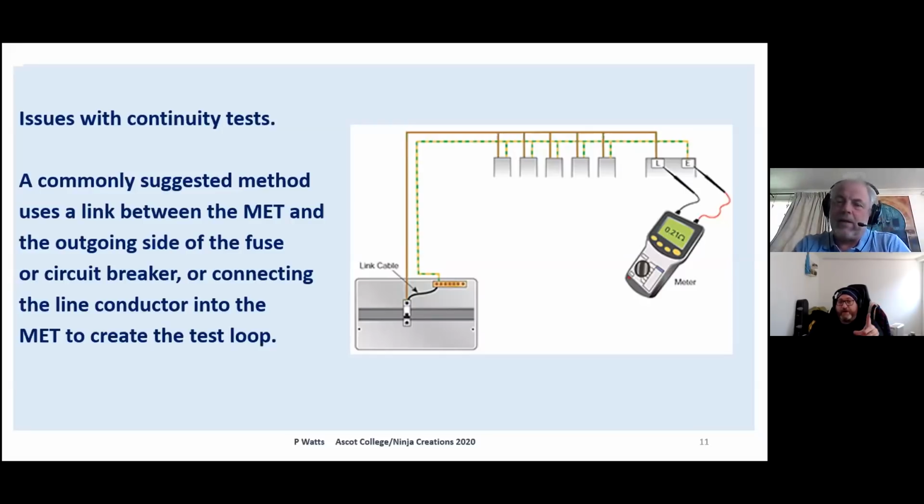We plugged it in because the site had this system where everything that was coming to site had been tested and checked, and that system had been in place. It was brand new. The person checking it didn't take that link out. It came in on site with all the certification, all the documentation. What do you expect it to do? You expect that the thing is all okay to plug in. Plugged it in, bang. And I've also seen apprentices leave the link in when we're doing it in the workshop. So hang on, I'm not happy with this way. That's just me personally.